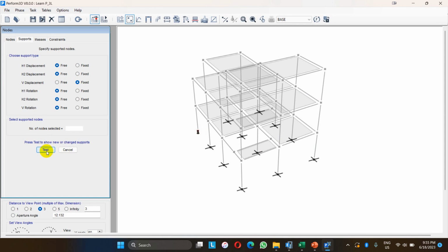this one, vertical displacement. And if we select some nodes, let's now I will select this node. Yes, this one is the roller. And for example, another hinge support like this. Yeah, this one is the hinge support. This is the roller support, this is the hinge support, and this is the fixed support. And like this, we have to assign the support condition for the structures, for the base or any other places if we have to assign the boundary condition.